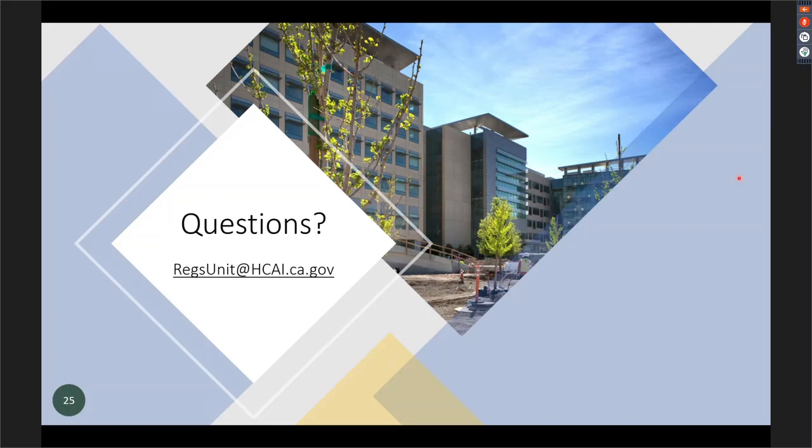Richard, the next question says, if one sheet has several details and there are changes on multiple details in the sheet that do not materially alter the work, do we need multiple NMA numbers on the same sheet? Again, it depends what the change is. If you're changing the substance of each detail, I would expect a new NMA so each one can be looked at. If you're changing, say, the type of screw on 10 details, that's one change.